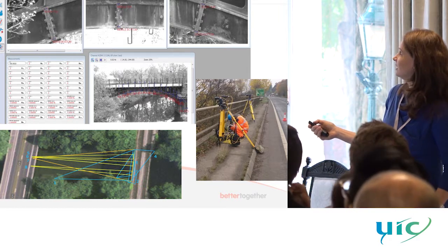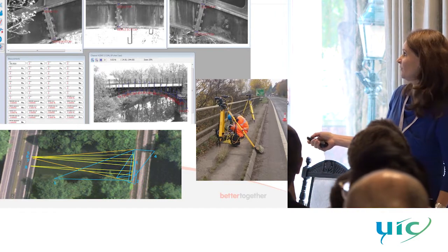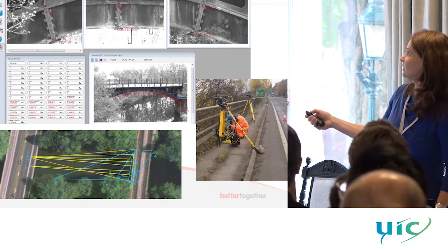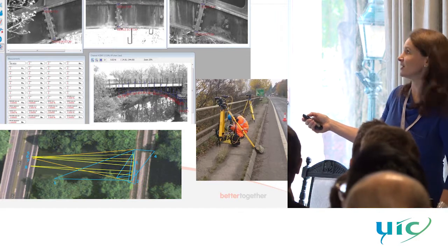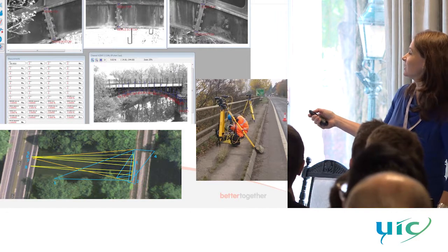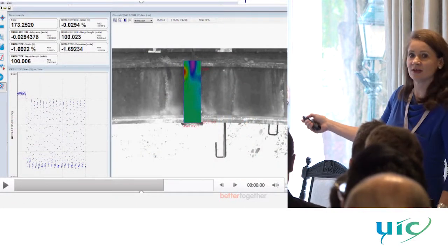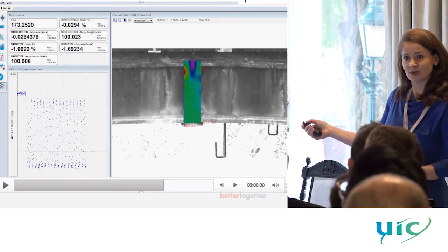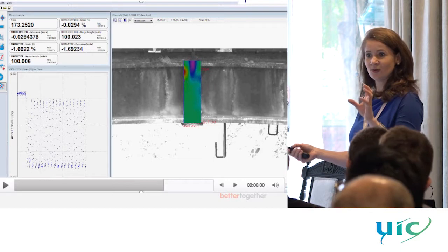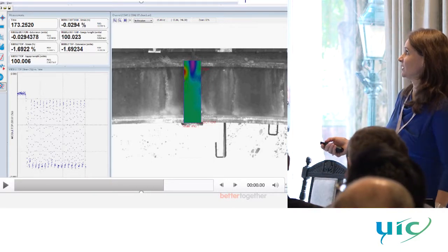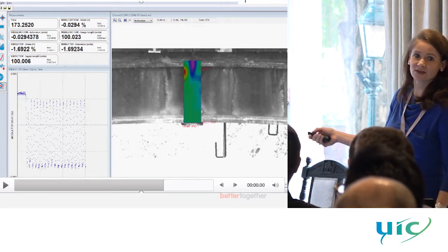As an example, a bridge was filmed from about 50 meters distance. Three cameras were put up, each of them looking at one detail on the steel arch at the bolt. And this is what you get. You get a picture with the strain distribution. So it could be helpful, just in case you need it, to look at any particular detail. And they also identify the loading and deflection.